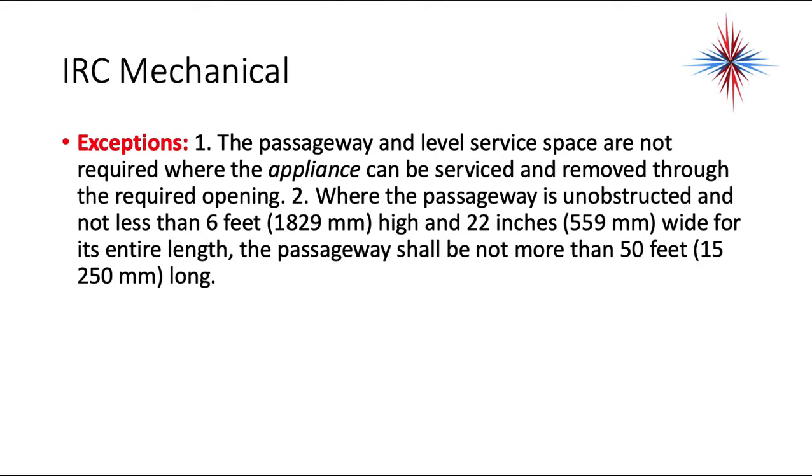The other way is where the passage is unobstructed and not less than 6 feet high and 22 inches wide for the entire length. Okay, in other words, if you can walk across an attic with a 6 feet height and 22-inch width for the entire passageway, and it's not more than 50 feet long to the equipment, you don't have to have the solid level floor.